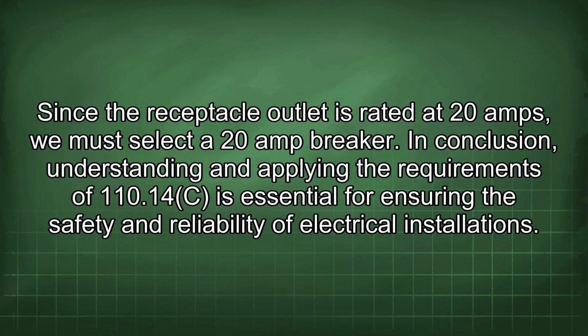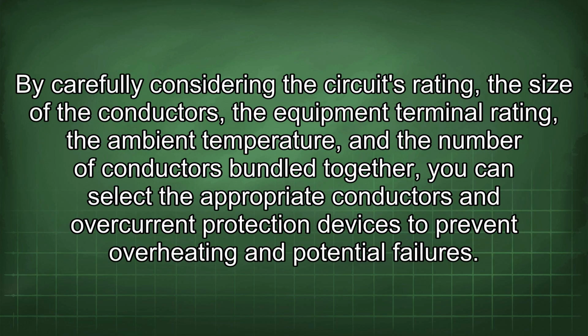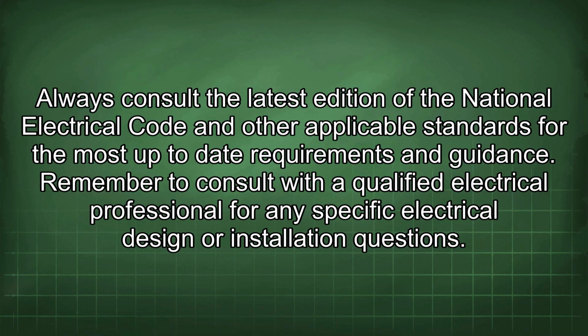In conclusion, understanding and applying the requirements of 110.14(C) is essential for ensuring the safety and reliability of electrical installations. By carefully considering the circuit's rating, the size of the conductors, the equipment terminal rating, the ambient temperature, and the number of conductors bundled together, you can select the appropriate conductors and overcurrent protection devices to prevent overheating and potential failures. Always consult the latest edition of the National Electrical Code and other applicable standards for the most up-to-date requirements and guidance. Remember to consult with a qualified electrical professional for any specific electrical design or installation questions.